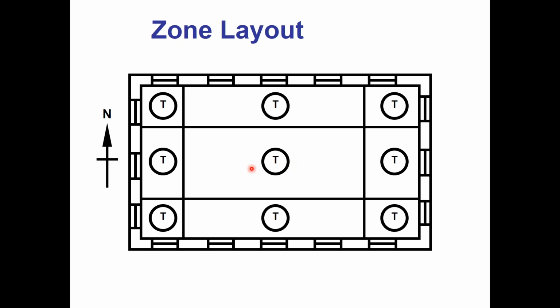One of these spaces might be a conference room, right? Maybe there's a conference room that's literally right here. So if I put a conference room in there, I no longer want that conference room in this area right here to be grouped in with the rest of this zone. Because that conference room at any given time could have 0 people in it, or it could have 15. So that guy is going to be a unique space, and I'm going to want to have him be controlled separately.